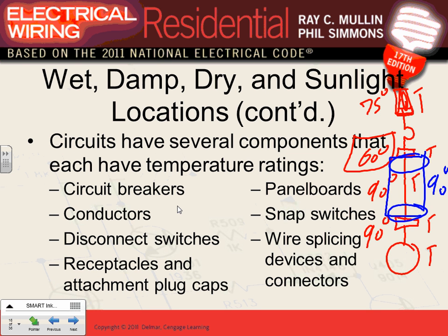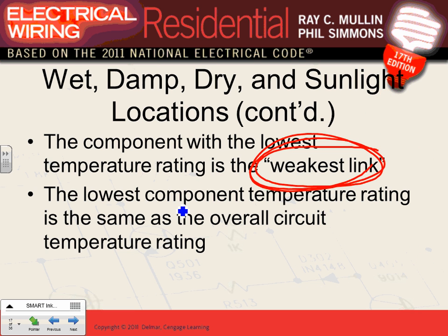If you do a high voltage, like a medium voltage system, and you're sizing your conductor based on 105, and your conduit cannot handle it, it's a PVC conduit rated for 90, then you have to limit the conductor to 90 because of the conduit. Typically, non-metallic conduits like PVC also have a temperature rating. If it's steel conduit, not a big deal.